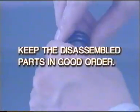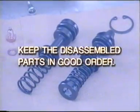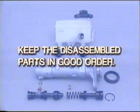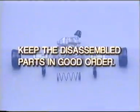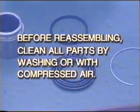Keep the disassembled parts in good order. Be sure that the cylinder cup and other rubber parts, inner surface of the drums, linings, pads, friction surface of the rotor disc are free of oil or grease. Before reassembling, clean all parts by washing or with compressed air.